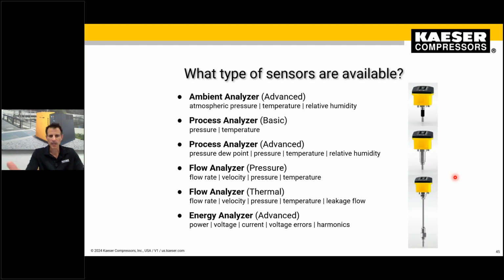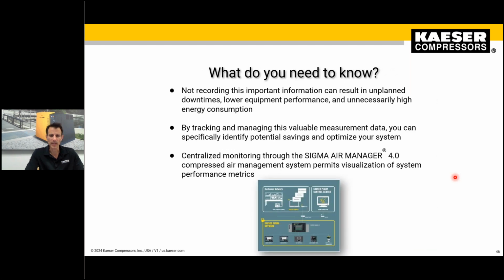So the ambient, we had that discussion in regard to the ratings of compressors with Andrew, ACFM versus SCFM, and the ambient analyzer will help you determine that with atmospheric pressure, temperature, as well as relative humidity. It'll give you some indications on how good or poorly the actual compressor room is performing, and also how your station is going to be performing as well.